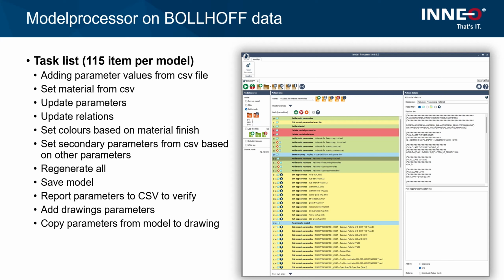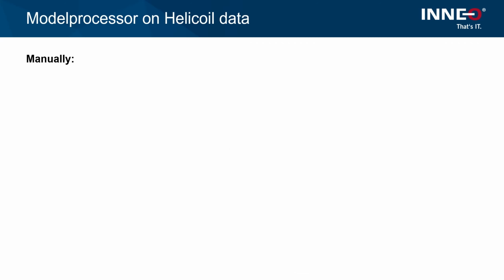We also copied information from the model to the drawing so that you could see it in the actual drawing itself, or inside Windchill for that drawing. We had to replace some drawing borders as we went along with this whole project, so they made some changes based on the different languages, where they've got some text they wanted in German, some in English, or a combination of the two. And then we had to update all the sheets, save all the drawings, and also create step files for all these items.